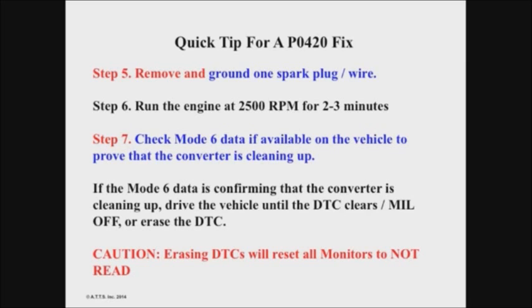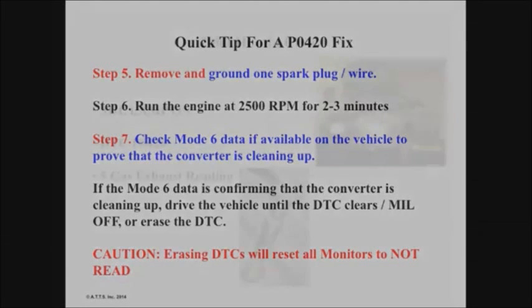Sometimes erasing DTCs resets all the monitors, obviously, all the time, I should say. Sometimes if you read the enabling criteria, you may not want to erase it and just drive the car in the criteria for that particular monitor, meaning the cat monitor. Yeah, just a real quick note there.